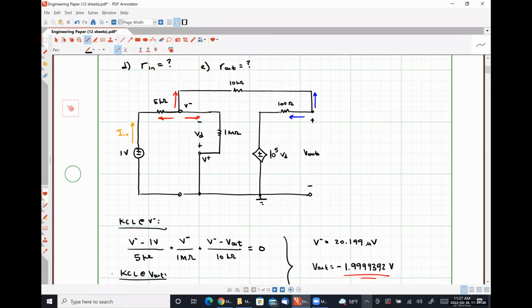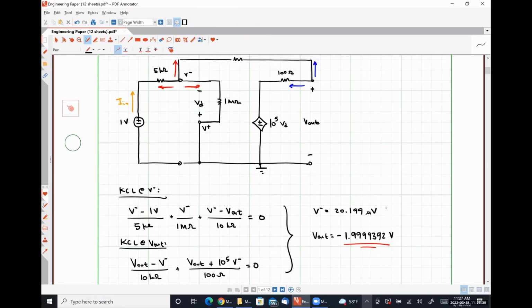Okay. All right. Yes. With these practical configurations, can you not consider that the current's not going to flow basically through that 1 megaohm resistor? That's like idealized op-amp behavior where that current doesn't flow. Right. So in this particular instance, we did include it. It's this contribution right here. If we ignored it, which is what we will start doing when we deal with an idealized case, as you suggested, we'll find that this quantity V minus is exactly 0, and this output voltage is exactly -2.